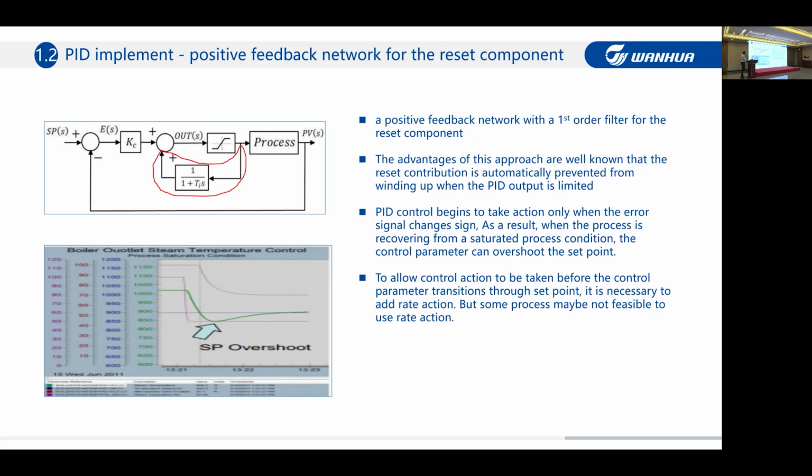The advantage of this structure is that you don't need to care about saturation. As long as the output hits the limit, the reset function is stopped. This is the big advantage of this kind of arrangement.